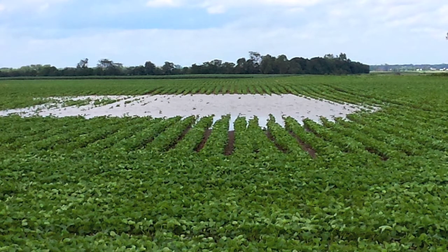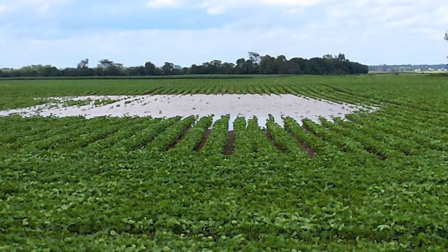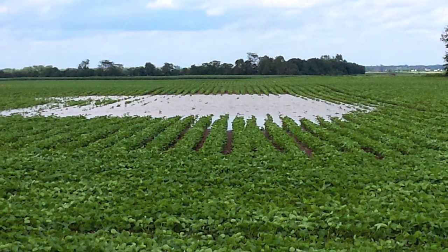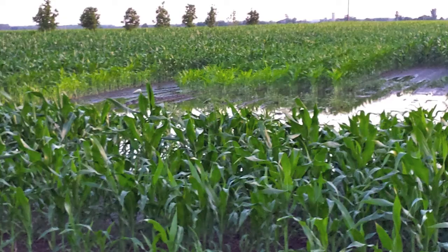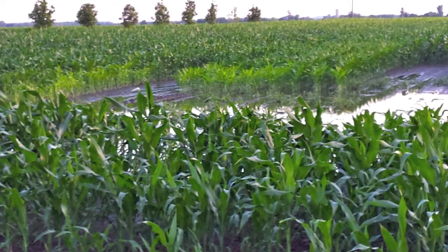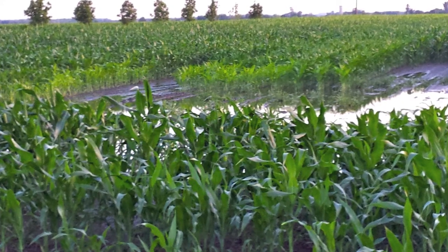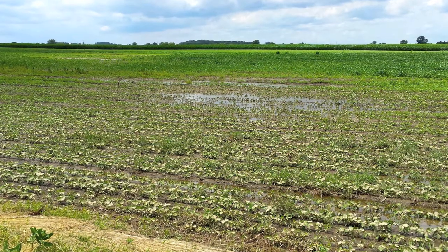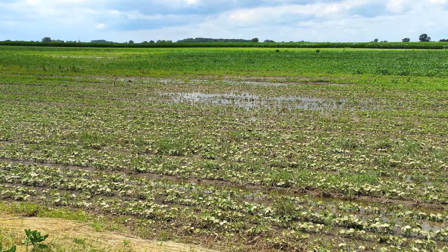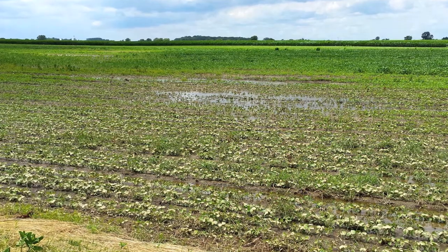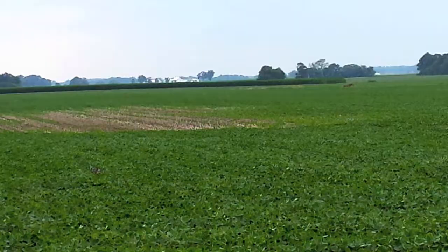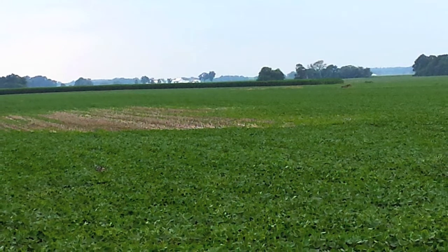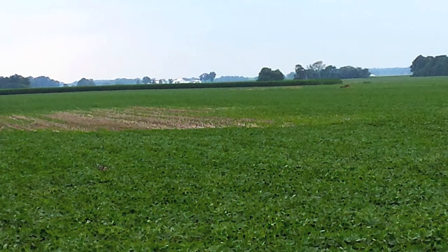We are told the possible reasoning for our continual ponding in these depression areas is that ponding water is weight. Weight on top of the soil causes compaction. Compaction forces air out of the soil, and beneficial soil life and crop roots need air in order to grow. Combine all of this year after year and those depressions become slightly larger over time and diminish yields, if we have any yields at all. Compaction can also reduce or deplete water infiltration getting down into the existing tile.